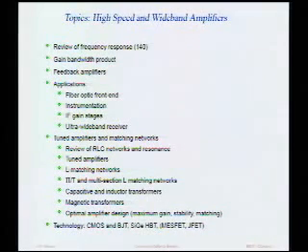In particular, we're going to be really concerned with bandwidth. We're going to try to design amplifiers that have as much bandwidth as possible. We're also going to be very concerned about operating at higher frequencies. We're going to try to figure out how to build amplifiers that work at the highest possible frequencies. What are the limitations, basically? Why can't I take a transistor and operate at 100 gigahertz? What's the limitation? If I had to change the process, what would I change in order to allow me to operate at these higher frequencies?